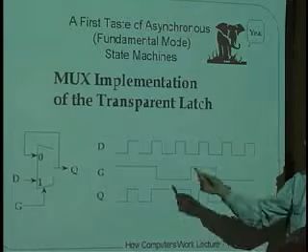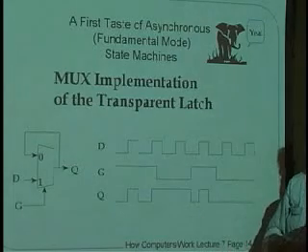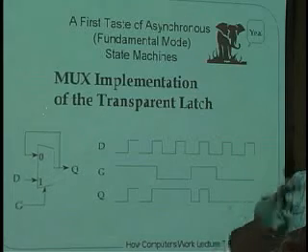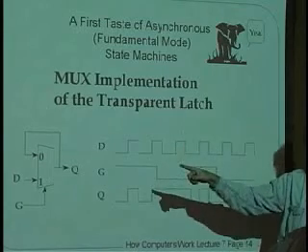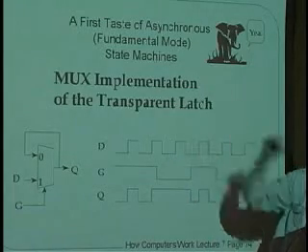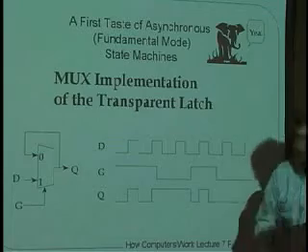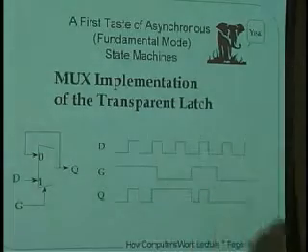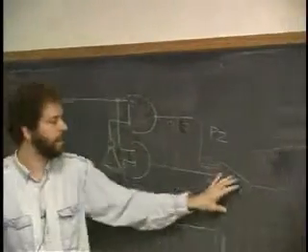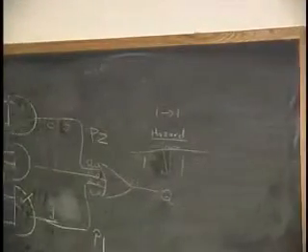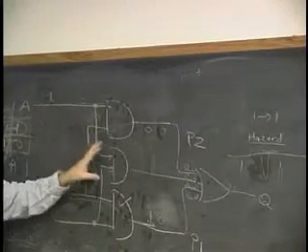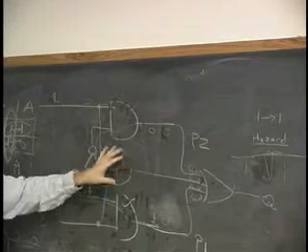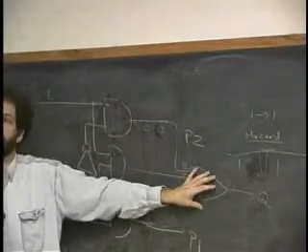Absolutely right. If I built this selector out of a physical switch, like a knife switch or a toggle switch, and I just hook that wire from the output back around to the input, of course the wire's not going to sit there at a high voltage all by itself. But it's not a wire. It's a set of gates. So this A is going to come through a logic gate and another logic gate and be wrapped around. So there are electronics that are in the path. And as we're going to learn about in class next week, these electronics actually have some amplification to them.